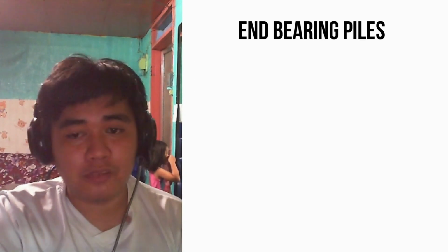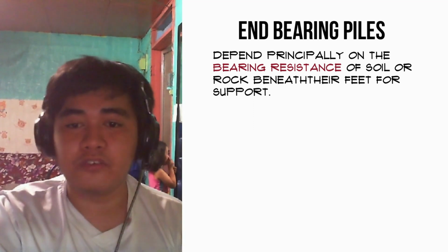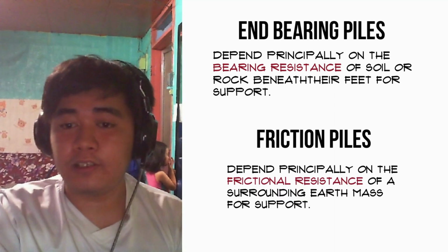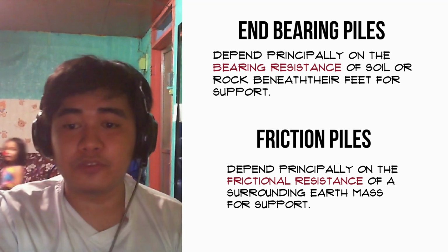End-bearing piles depend principally on the bearing resistance of the soil or rock beneath their feet for support. Friction piles depend principally on the frictional resistance of a surrounding earth mass for support.